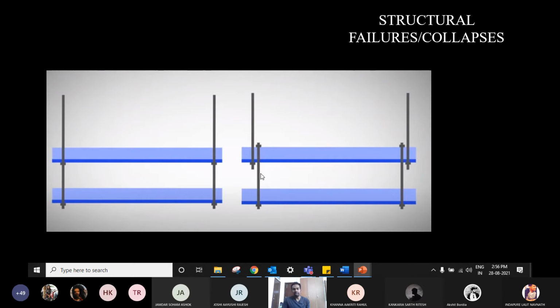Now again, this needs to be verified and signed by the designer. He needs to look at all the shop drawings created and check if this is okay or not, and he gives an approval and stamping on each fabrication drawing, and then work is carried on. You get that to the fabrication yard and start making those components, or if it's concrete, you start pouring the concrete on the site. Now this was a proposal given in the shop drawings by the contractor, and the structural engineer approved it without verifying it.